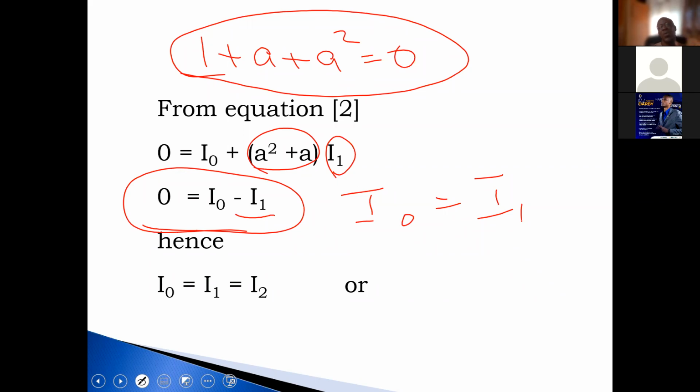And if I substitute this relationship back into equation 1, because remember equation 1 just told us that IA was equal to I0 plus I1 plus I2. We had that IB and IC were equal to 0 based on the boundary conditions.